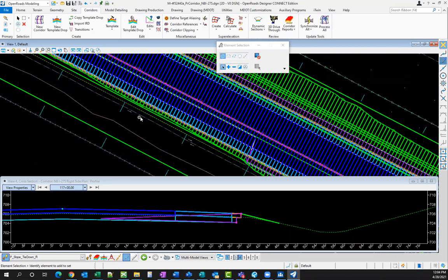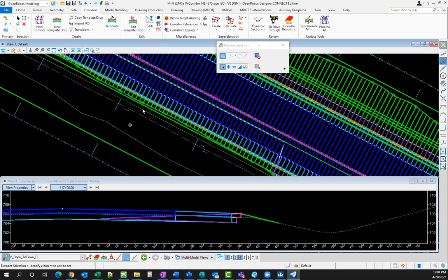But what ends up happening in this situation is you will end up with like a 1-on-4 or flatter slope in this instance. And I know that the design reviewers don't necessarily like to see that, but at the end of the day, that's really what's going to get built. They're going to daylight this out, and whatever this slope is, that's what it is.